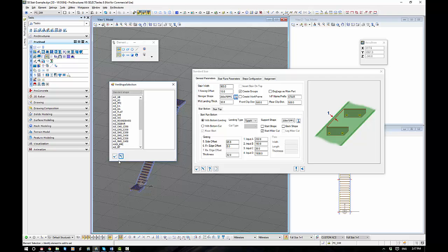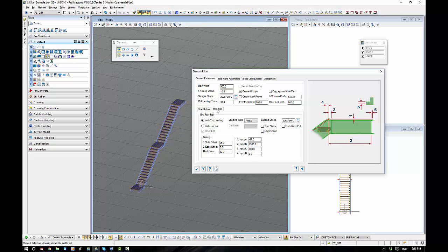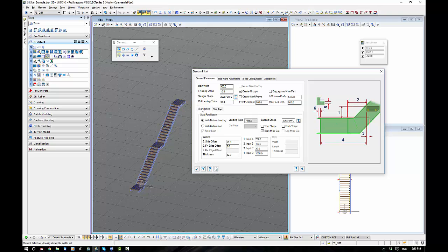By standard it will be PFC. Okay. We can create a group on the fly as well as have an individual work frame for the stairs, but I've opted to have this switched off. Okay. Other things to bear in mind is your landing thickness will mean your grating thickness. There's a couple of different places where we'll need to put that in. Okay, we actually alter both the stair top and stair bottom at the moment, so we'll kick off with what happens down the bottom of the stair.